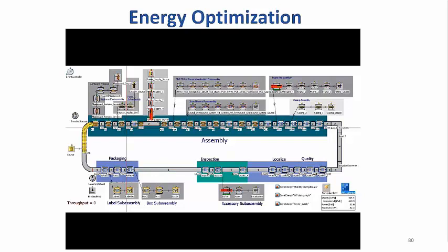We'll run the model slow for a while so you can see everything in action, starting with the first skid being placed on the main line and throughput statistics being collected when the screens are removed from the skids after the packaging line. After 1 day of simulated time, you can see that our throughput is the optimized value of 1,976 screens that was mentioned before. Since we added energy inputs for our stations and conveyors, the Energy Analyzer's display panel also provides valuable overall statistics, including 1,899.7 total kilowatt hours of energy consumed.